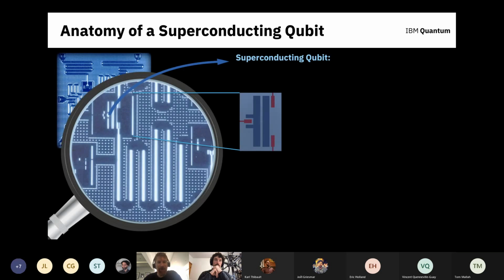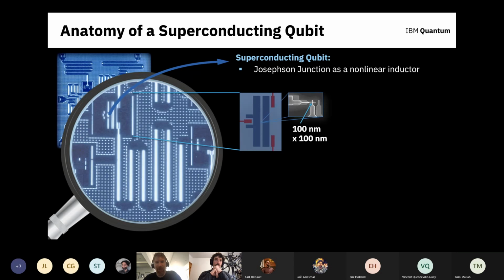And the qubits live inside these square pockets and pretty much look like equal signs that have been rotated by 90 degrees. That equal sign actually represents the capacitor of the qubit. And if you really zoom in, the aluminum features consist of something called a Josephson junction, which is a superconducting-insulating-superconducting interface. And that electrically behaves as a nonlinear inductor. So we kind of have a nonlinear LC oscillator at this point.